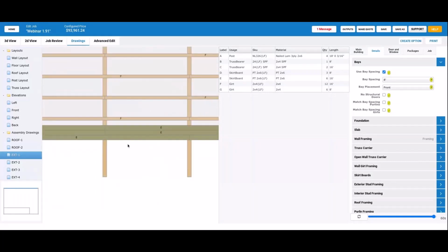So they don't want the steel hitting against the treated lumber because the treated material corrodes the steel. No kidding. So could we get away with the bottom two are pressure treated and anything above that is this other material? I don't know, but that makes sense.